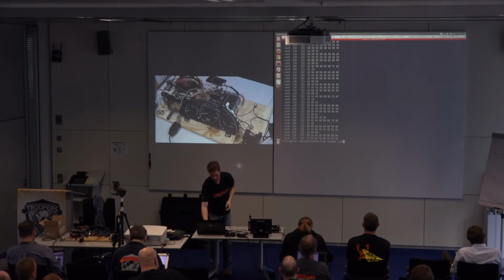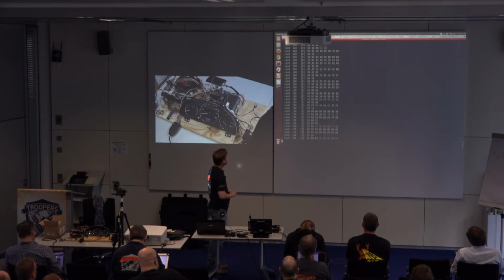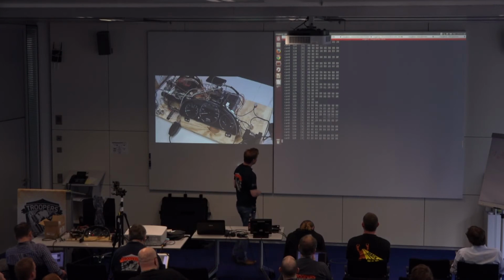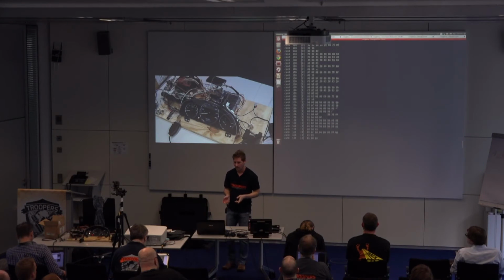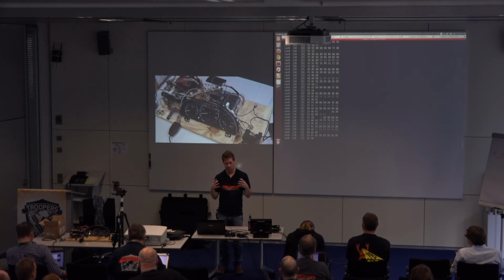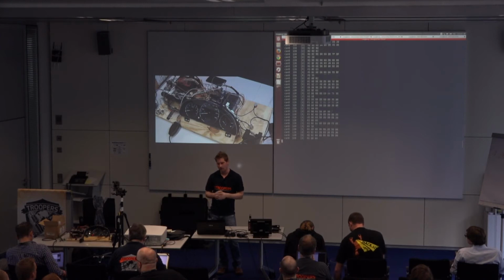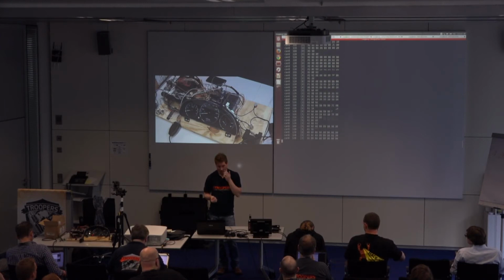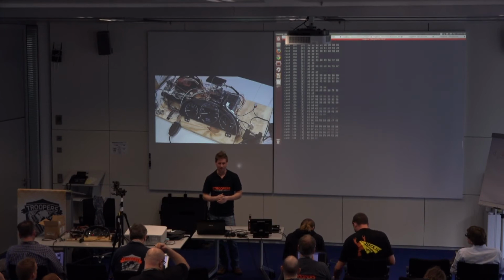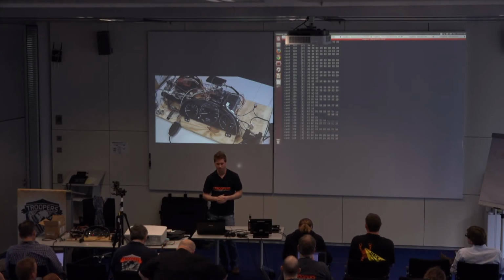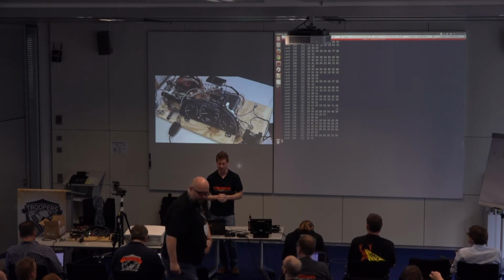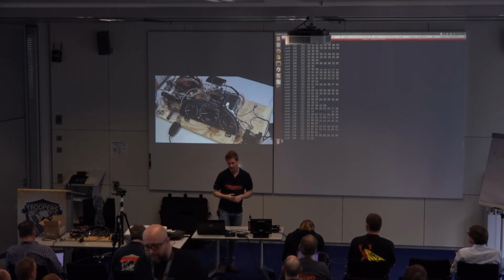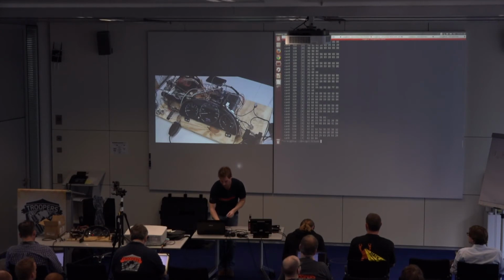But this view, as you notice, kind of sucks. And this is why you can use Wireshark. This is also a good reason why you wouldn't want to, because just too much data is flowing through. If you've ever used Wireshark, when it takes things apart, it's called, I believe, a dissector. If you're going to write one for it, that would be fine. But because it varies for each make and model and even year, you can't write a dissector for each one of them. There's not a real good way in Wireshark to say, now I'm on a Ford Fusion, and now I'm on a GM vehicle, and just have it change the dissector. So it doesn't work very well, and it just constantly scrolls.